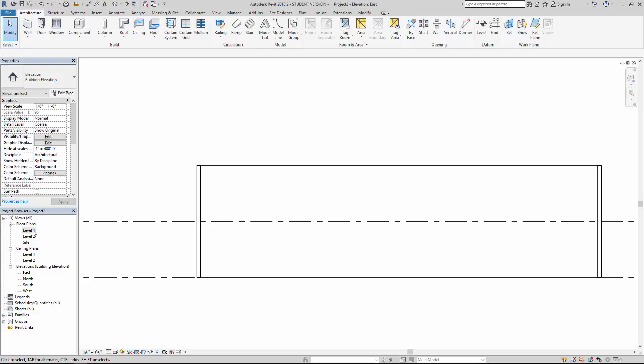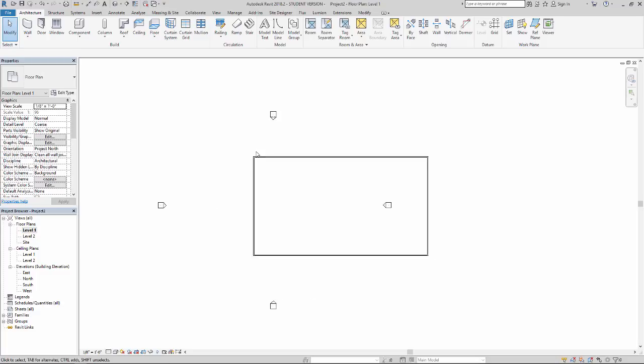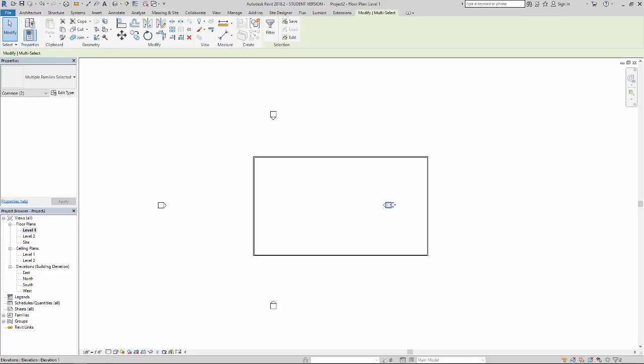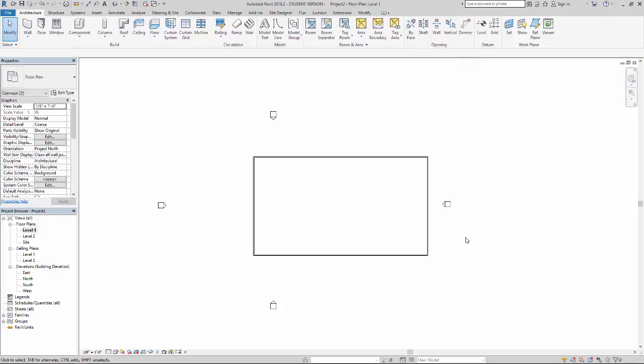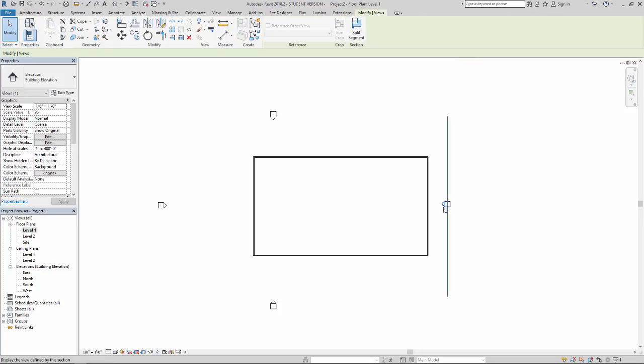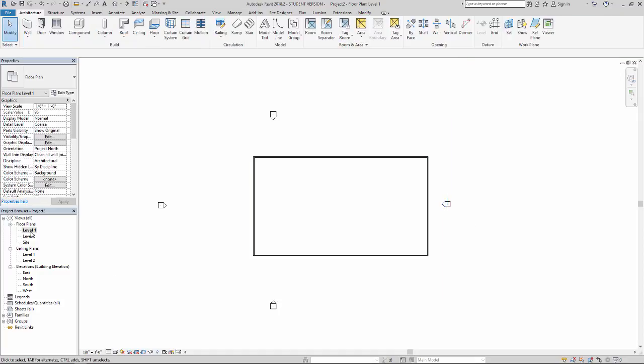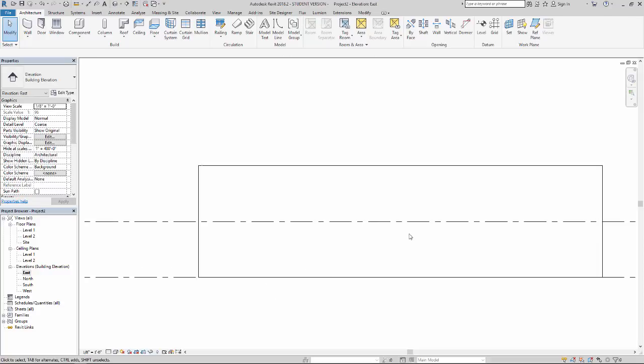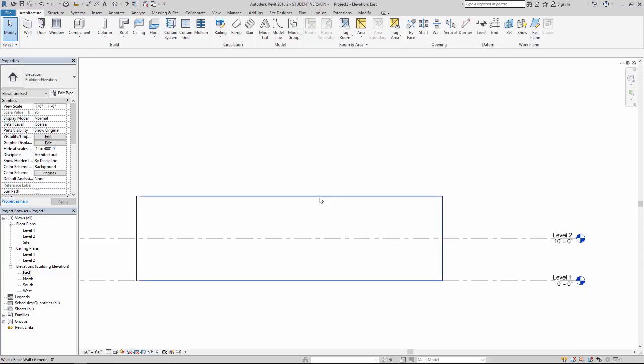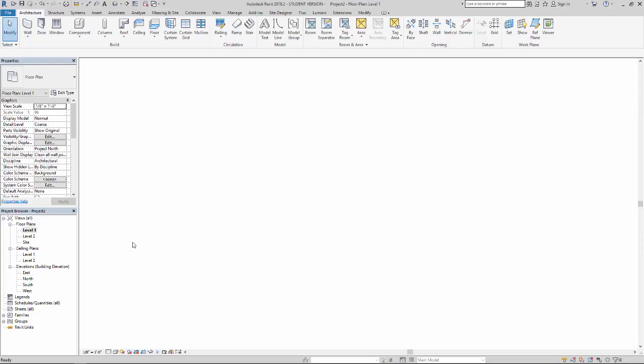you can see I'm actually cutting a section through both of those walls. So as you're starting a project, typically you want to be in the center of this area. But if your project begins expanding past the border of those elevation tags, you want to make sure you're moving them outside of the project, both the icon and the section line, because those two pieces can move around independently. So I'm moving that section line by clicking on the triangle and moving that box around. And now if I go back to the east elevation, I'm seeing that set of walls now in elevation. So just be aware of that as you're starting out.